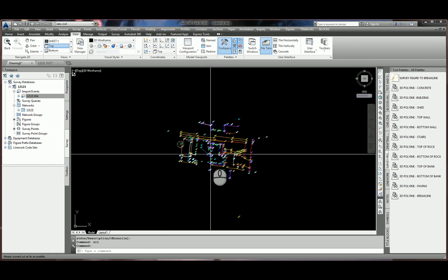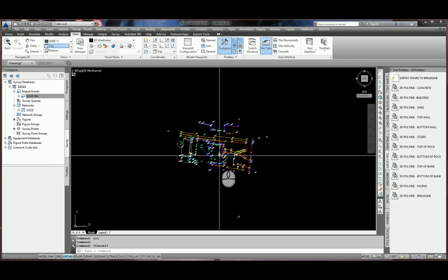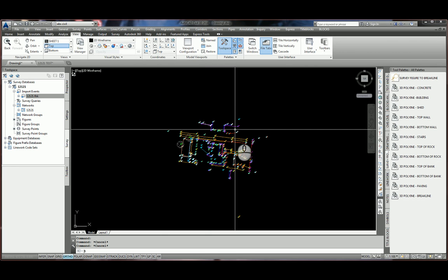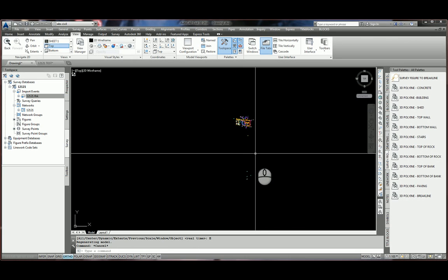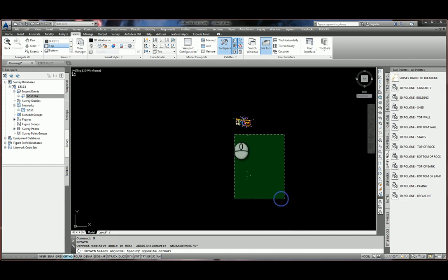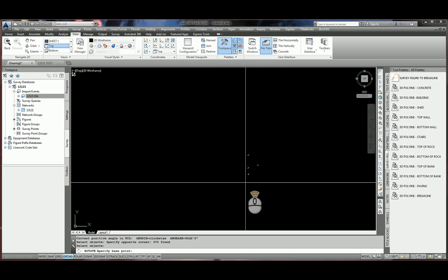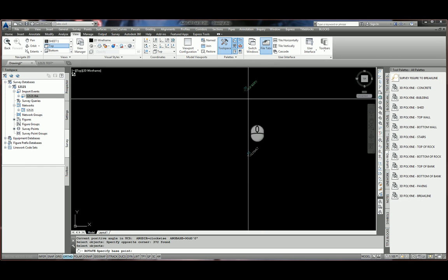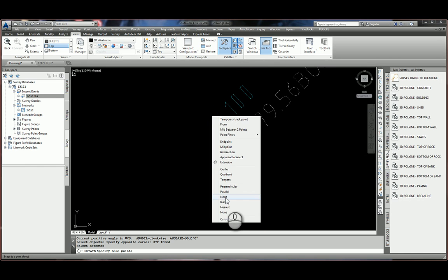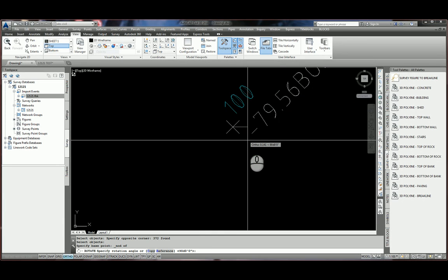Once you datum shift, for example, I'm just going to make an example of this one. So I zoom extents, and I'm going to rotate. I know for this, I need to rotate all objects from this bolt, for example, and I need to rotate it 48 degrees, 36 minutes, and 25 seconds.